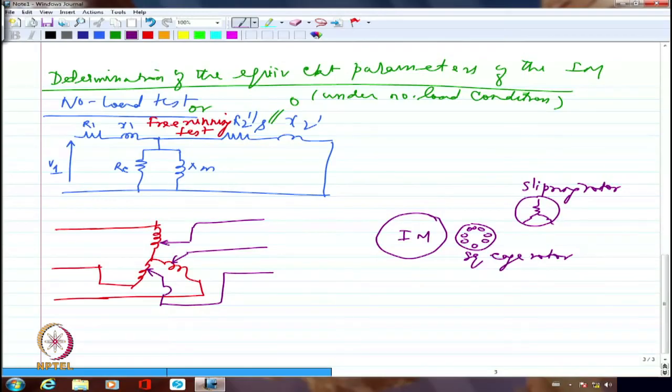Okay, so representation, I am just showing the representation. So this squirrel cage rotor, now please note I will not show any brushes. In a DC machine I will always show brushes in the armature. Here I should not show a brush. Now this will be connected through wattmeter and ammeter. And voltmeter, of course, we can connect, or a multimeter can do the job of measuring.